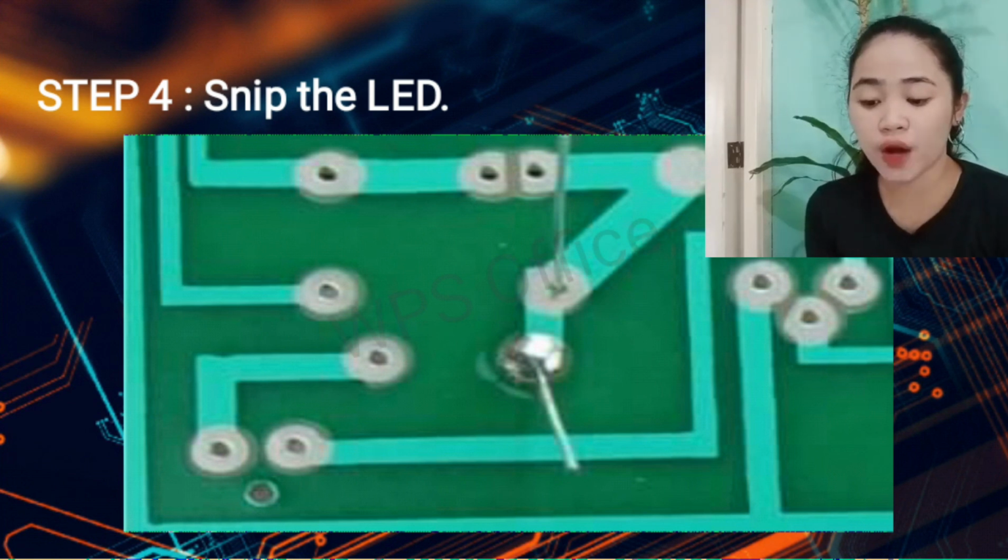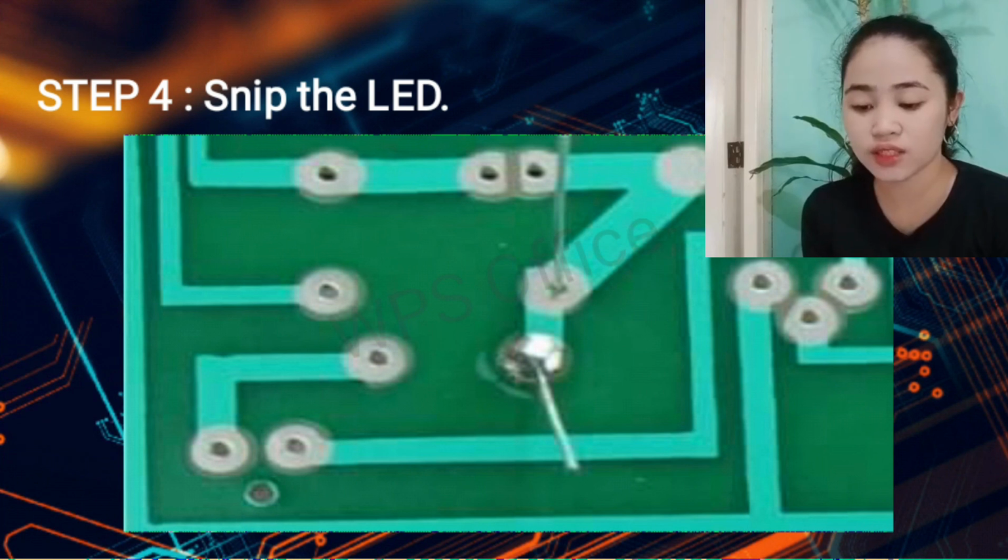A proper solder joint is smooth, shiny, and looks like a volcano or cone shape. You want just enough solder to cover the entire joint, but not so much that it becomes a ball or spills to nearby leads or joints.